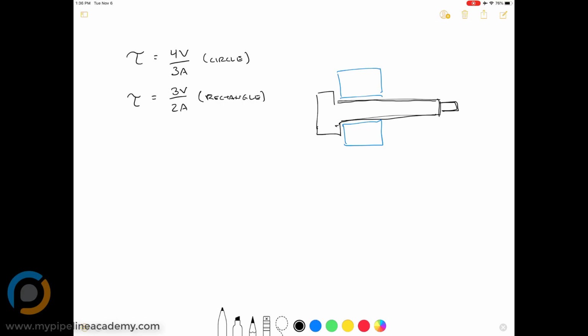Half of this shoulder bolt is in this blue part, and then the other half, let's say, is in this green part. And this green part is fixed out here somewhere. Then let's say that we have a load that's placed on this blue part right here. So this blue part is being pulled down, and the only thing holding the blue part to the green part is the shoulder bolt, which means we're creating a shear force right here in this area.